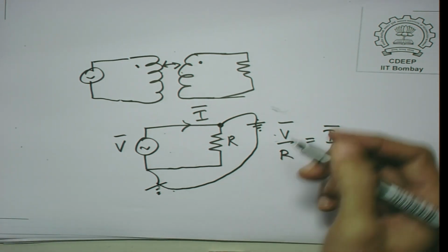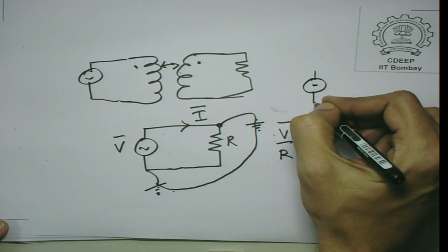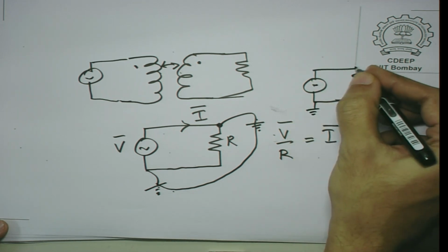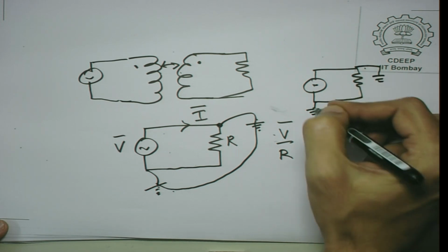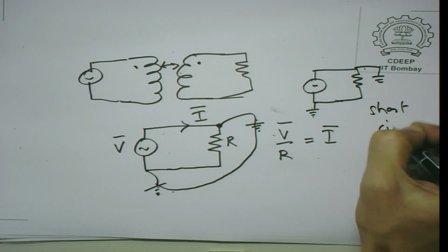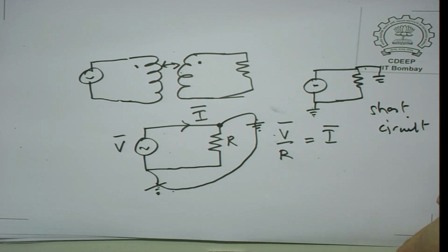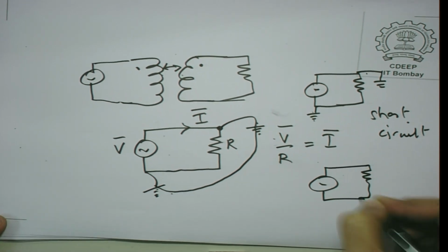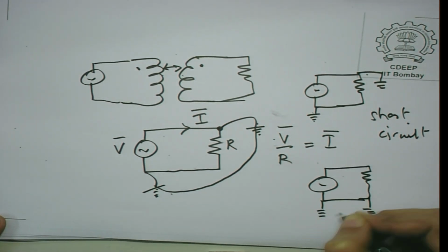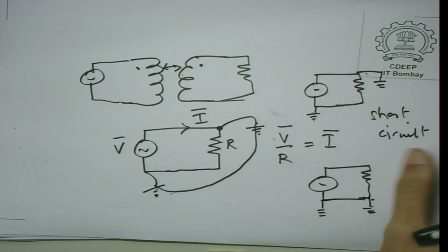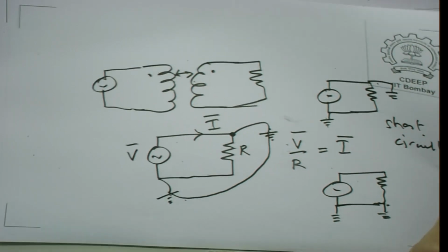So, I cannot just take 2 points and connect them to ground arbitrarily. Okay. So, I can't just connect this to ground and this to ground, this will actually cause a short circuit. So, I am not at liberty to do that. Of course, I can do this, it will not create a problem because even if I short it, there is a metallic connection here. So, this will not affect the circuit. Okay. But in fact, with a transformer you can do this. What can you do?